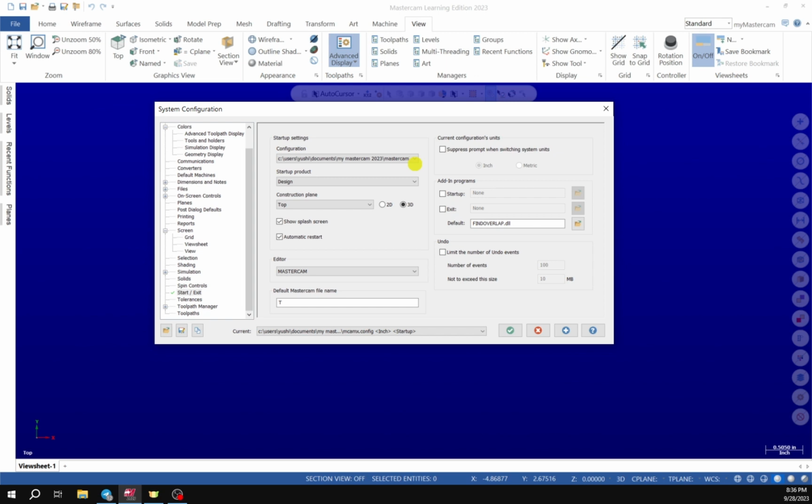However, sometimes for that period of the time that you are using the Mastercam, you may want to switch to metric system. That's when you come to current here. In here, if you open and select a metric system and you say OK and save it, for that session, you will notice the system measurement changes to metric.